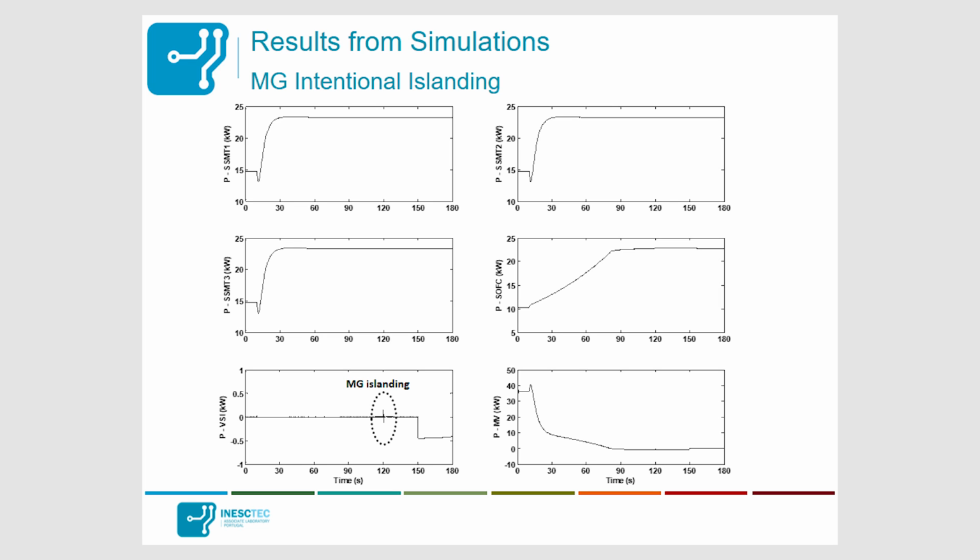So it is possible, in the first moments, to try to bring the active power outputs of the different devices to the values that will bring the power flow in the transformer of the medium voltage/low voltage substation to almost zero value.